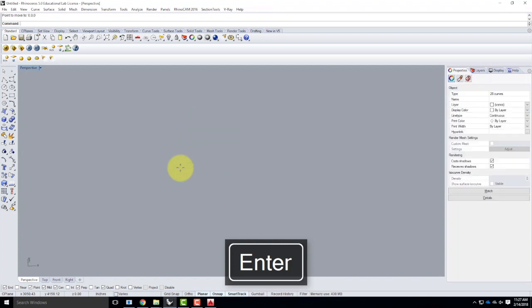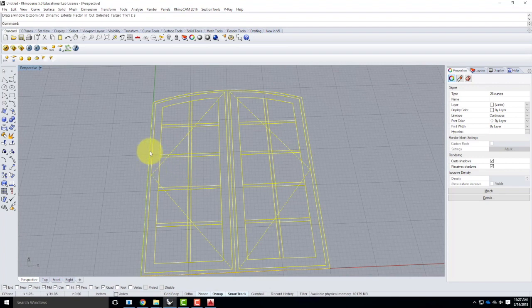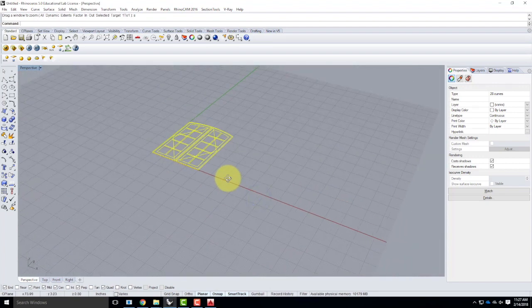And then enter, zoom, Z, followed by S for selected. There we are. I'm back at the origin, and I've gotten rid of all that other stuff. So I just took this piece of the drawing and kept that one piece. That's the only piece that I'm going to draw. Obviously, there's a bunch of different sizes of the window. I'm only drawing one today.